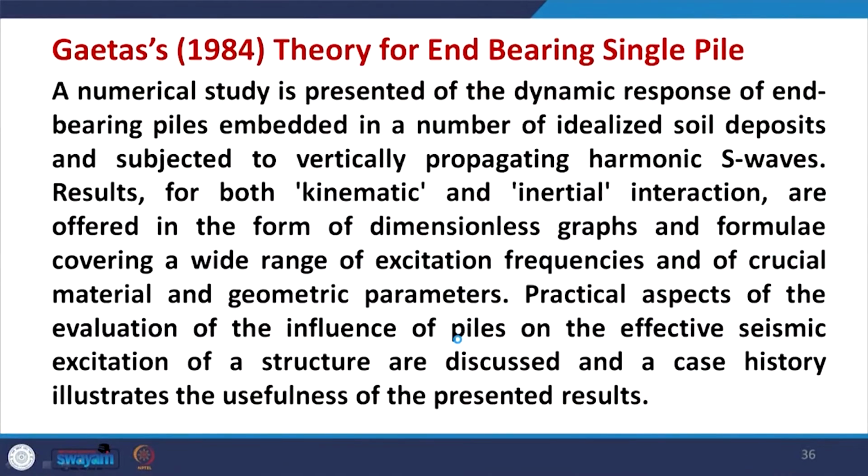So, a numerical study is presented of the dynamic response of end bearing piles embedded in a number of idealized soil deposits and subjected to vertically propagating harmonic shear waves. Results for both kinematic and inertial interactions are offered in the form of dimensionless graphs and formulas covering a wide range of excitation frequencies, and crucial material and geometric parameters are considered.